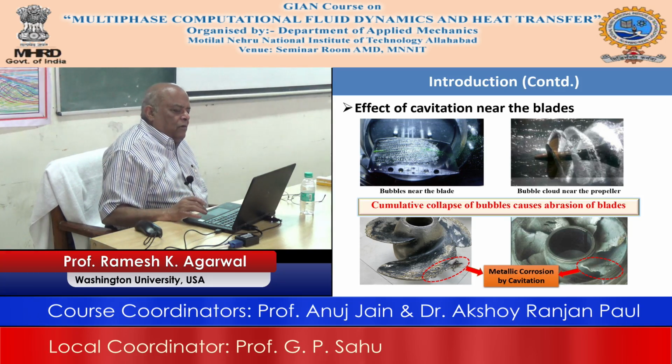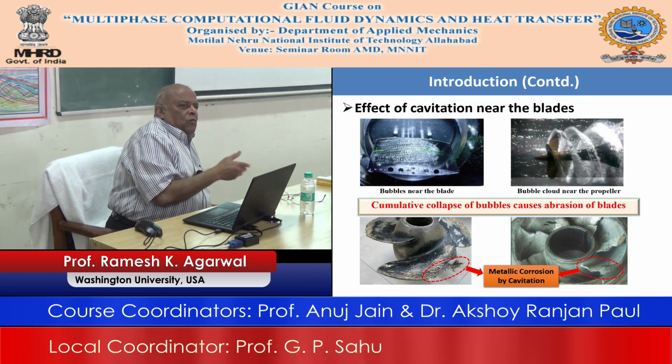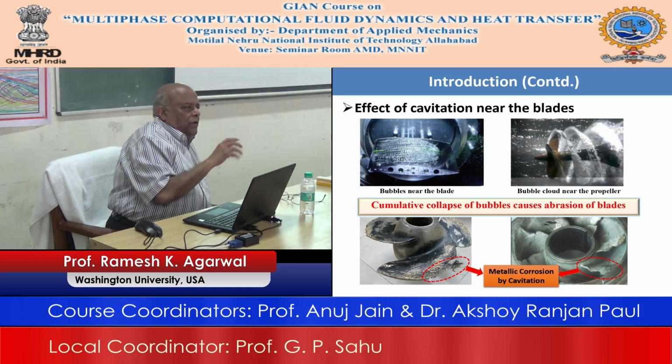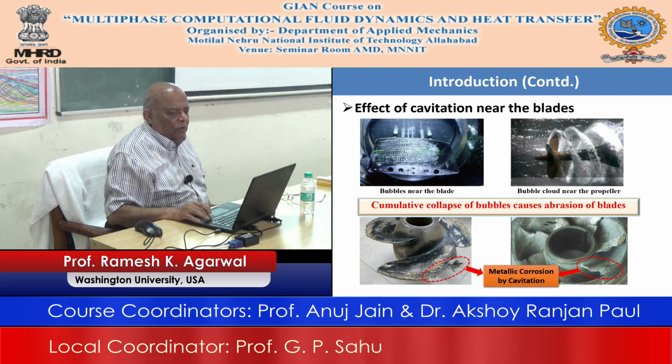And as I said, there is corrosion, and primarily in most of these applications, such as centrifugal pumps or turbo machinery, they all have a rotating part. One of the things that happens in rotating machinery is that the chance of the vapor pressure versus the pressure outside becoming so low that you have a chance of bubble formation increases. This doesn't occur if you don't have rotating machinery. That's why it doesn't occur that often, and so mostly people associate this problem with rotating machinery.